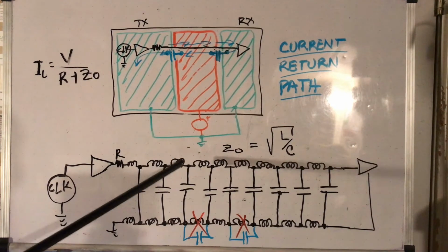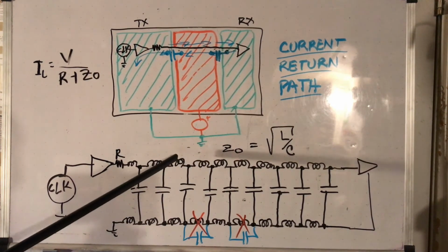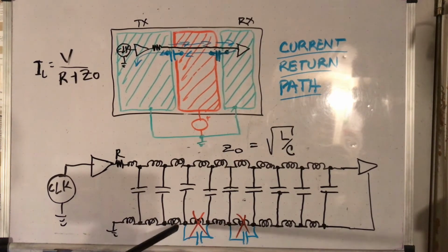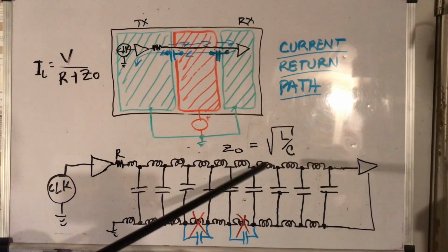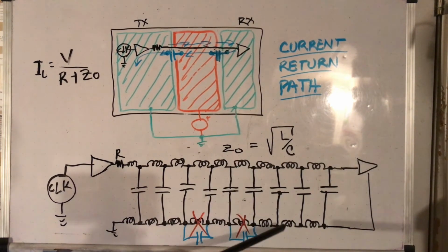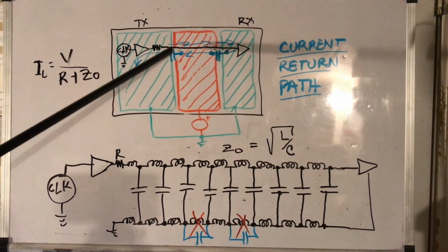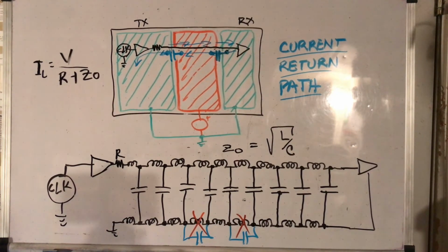The current is going here, where it finds the break, it can go through the cap back into the path that it had before, and so forth. Here, when it finds the next break, as it's flowing here, it can find a path to go, and it's right under the transmission line, so you put a cap there. And so that's why you bridge these gaps with capacitors, and that fixes the problem. That's what we have seen in our demonstration, and it worked rather well.